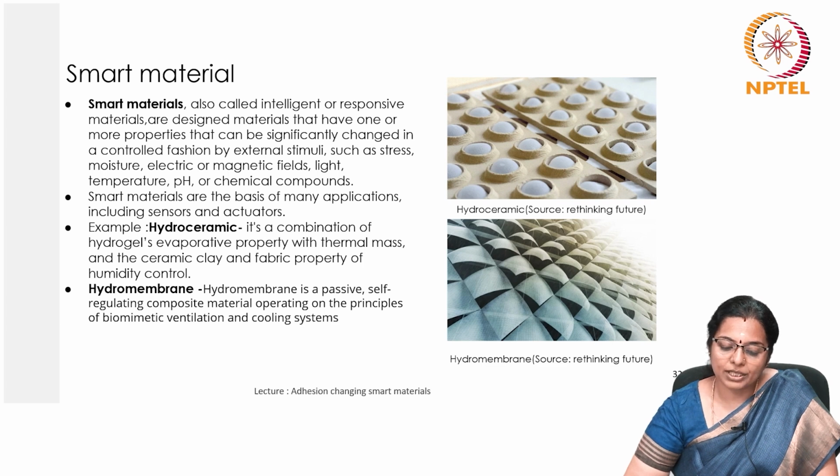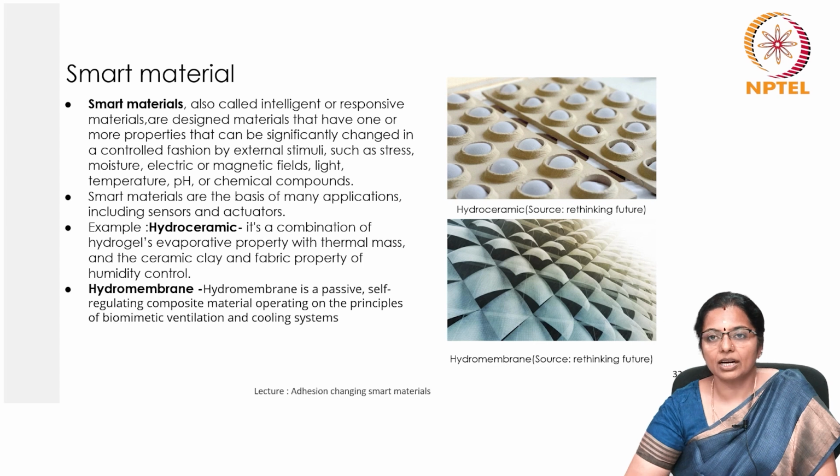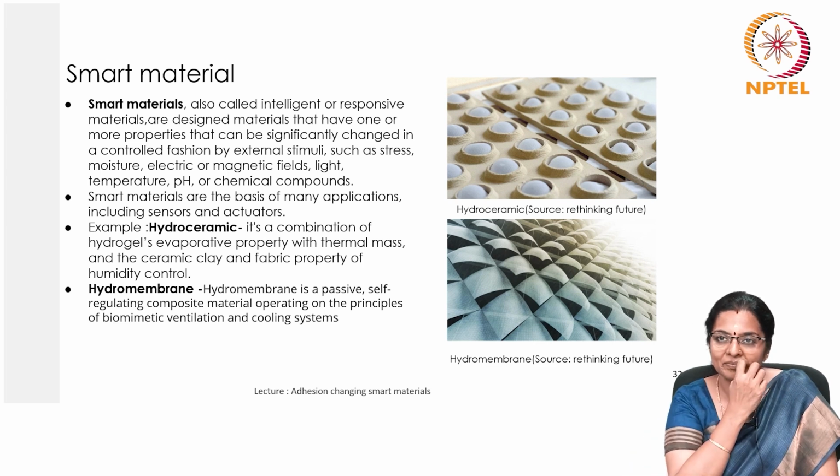Hydroceramic is a combination of hydrogel's evaporative property with thermal mass and the ceramic clay and fabric property of humidity control. If we look at hydromembranes, then hydromembrane is a passive self-regulating composite material operating on the principles of biomimetic ventilation and cooling systems.